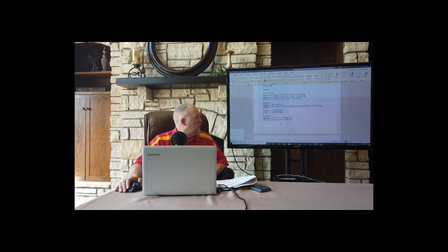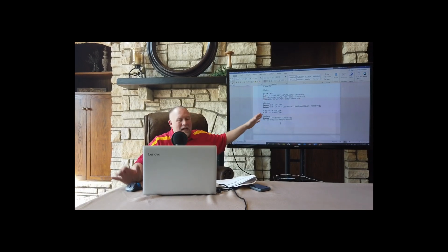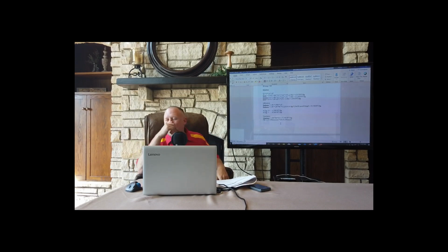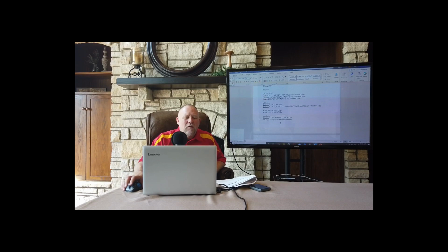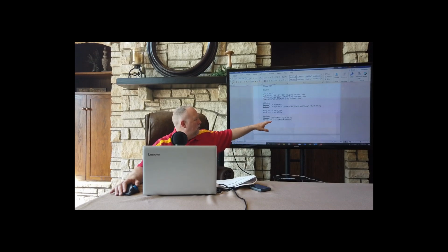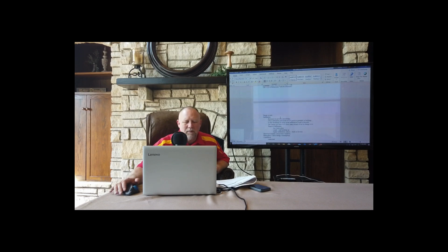Now notice, maybe though for that same area, what if this was an office? Yes, if this was an office, we'd have 17 CFM per person. But if it was an office space, maybe it's only 5 people in that 800 square foot area. So that ends up being drastically different. And here's some important takeaways from this.